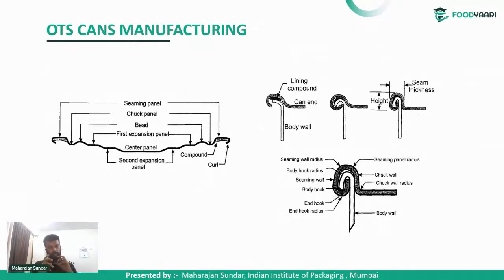Because, as I said earlier, the cans might or definitely will undergo retorting. During retorting, the product inside will expand. The metal containers actually transfer heat to the product, and in return, the product also transfers heat. This tends to expand the body surfaces, that is the body and the bottom closure of the metal container. This arrangement will prevent the base of the metal container from distortion.